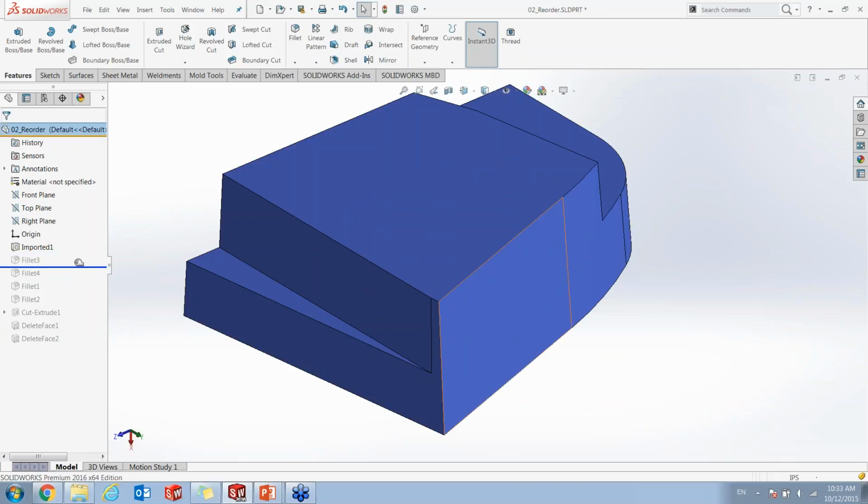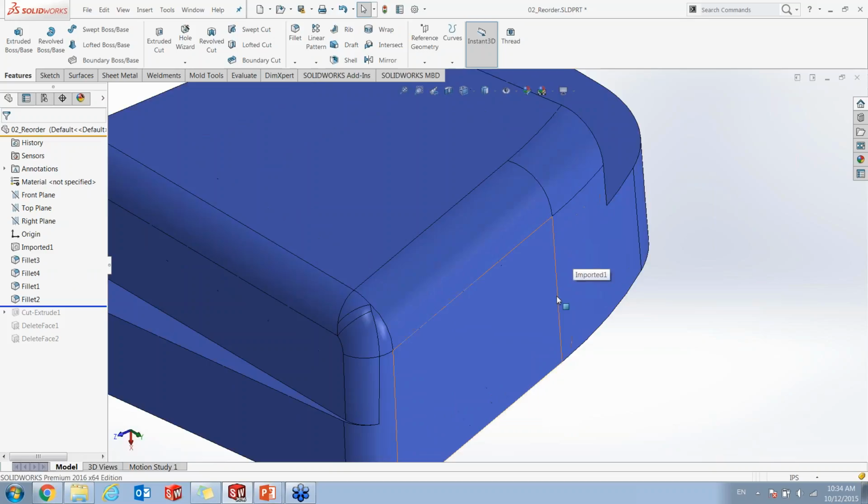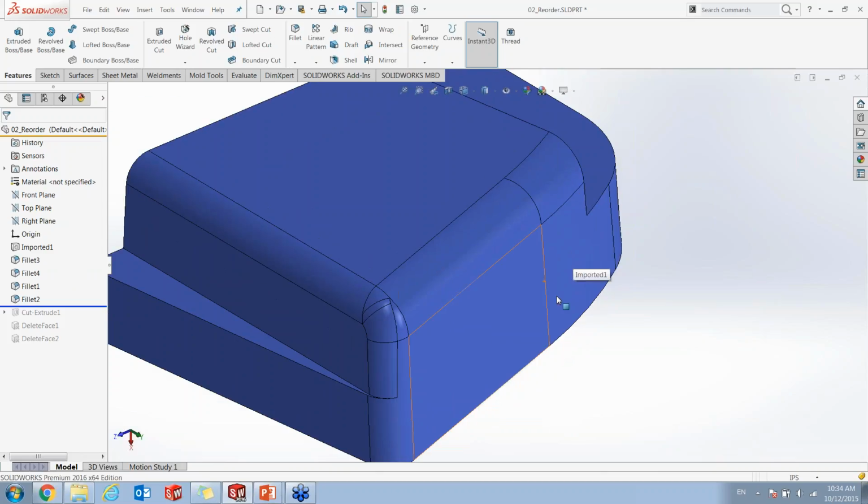Okay, so you can see the first fillet that we create is the large fillet. You are advised to create the fillet in this way, meaning you create the fillet for the larger value first. Then we put in 0.38, 0.225, then another 0.25, then the last one is the smallest value, 0.22. So you can see that we do not need to have any repair or identify the failure area and then repair it and then correct it.